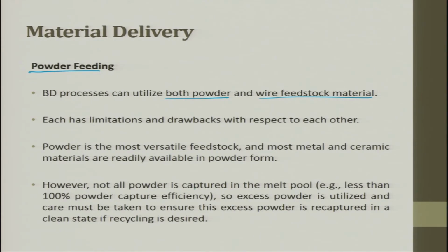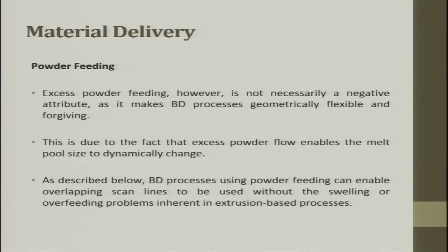However, not all powder is captured in the melt pool. So excess powder is utilized, and care must be taken to ensure that the excess powder is recaptured and cleaned if recycling is required. So that means, if you dump a lot of powder, not all of it will be melted. You will have only a track, along the track it melts, and the rest of the powder should be removed so that it can be used for melting.